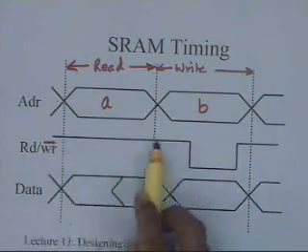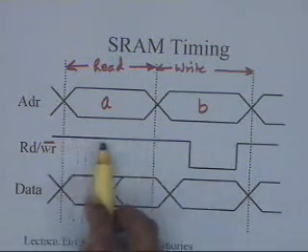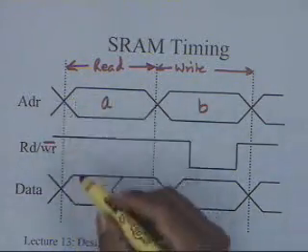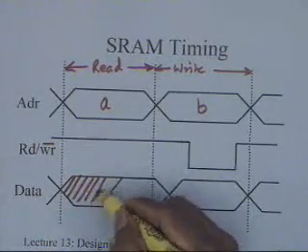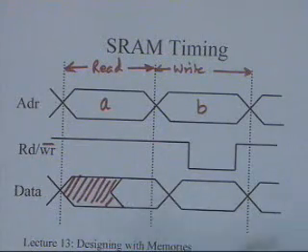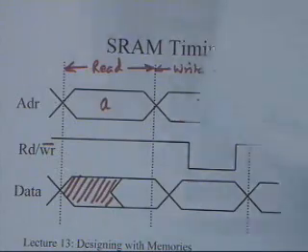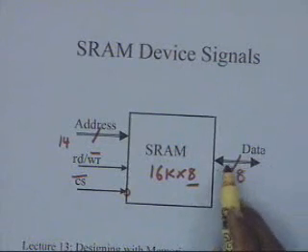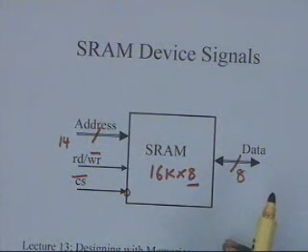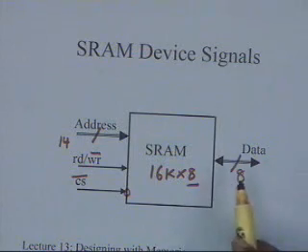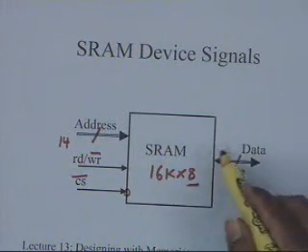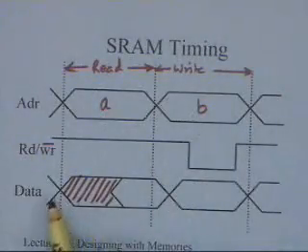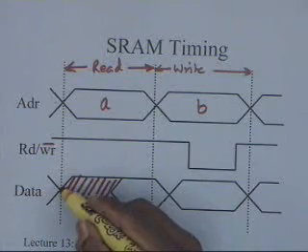So now during this read time, of course, the read signal is going to be high because this is a read operation. Now what happens is, once this address is given and read is there, this is the data output. Remember, it's a bidirectional data that I am using over here. These data lines are bidirectional, both the input is supplied on the same lines, output also comes on the same lines. In many RAM devices this is true, but there are some RAM devices where these two could be different. You can have a separate line for output and separate for input. I am considering that here.